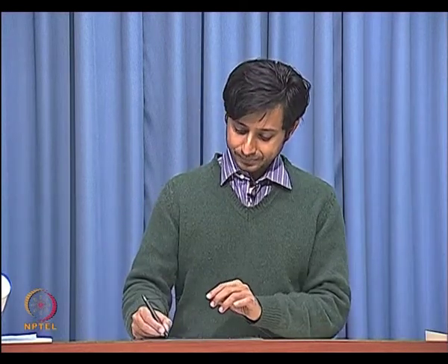These 2 bits are called up and down, and then we have some sort of a current steering DAC. I am going to call it a current steering DAC. If you look up the books, it is called a charge pump, and this digital value is converted to an analog representation over a capacitor. Now, if I just use a plain capacitor, then unfortunately the system becomes unstable, because there will be 2 integrators in a loop and I can't do that.